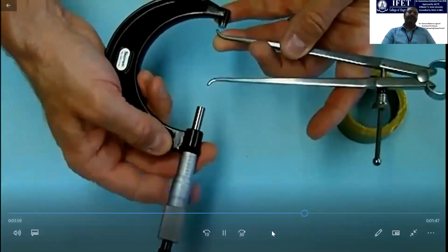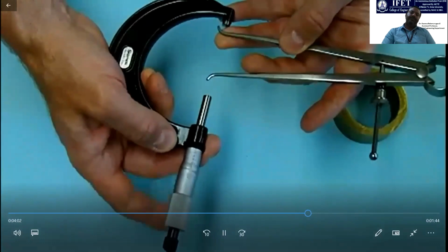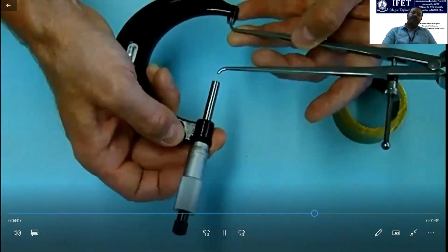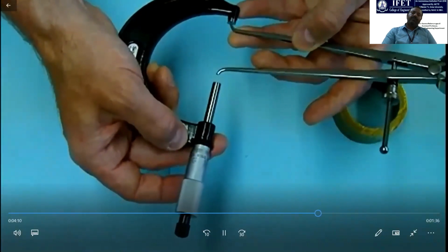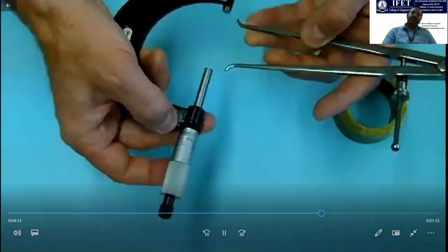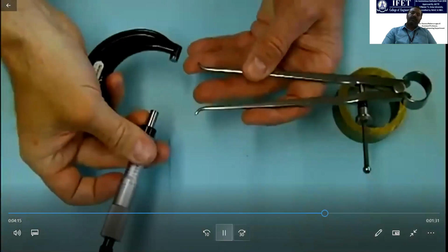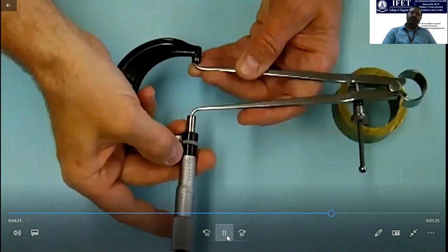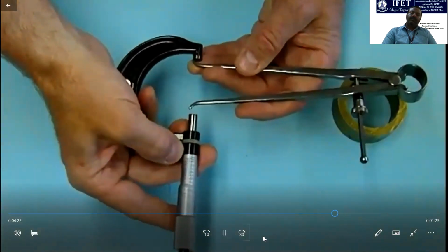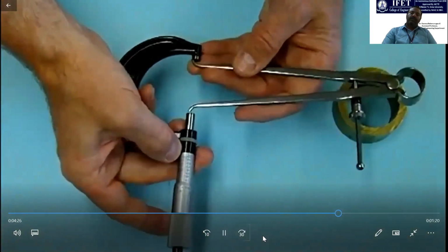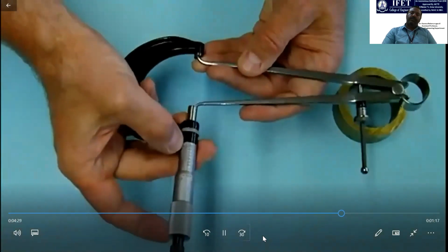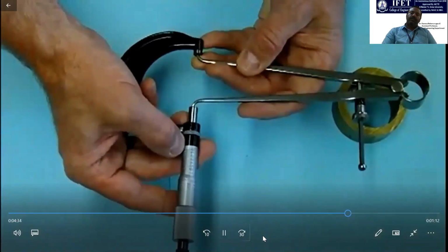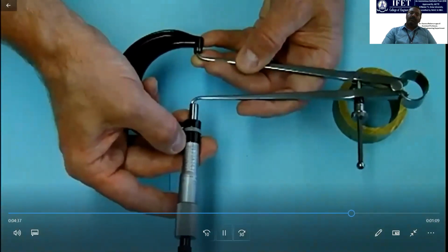In this case, I can choose a micrometer, and I can measure across the face until we get the size required. So what I would do is set it on the one leg, measure it back and forth and in and out. Again, now that we have the size of that bore, I would hold the one leg against the far end of the micrometer. I would start to move the thimble of the micrometer in towards the other leg as I'm moving the caliper across the measuring face and also back and forth across the micrometer till I get the same feel that we had inside the bore.